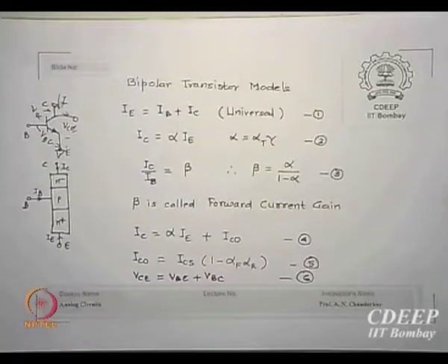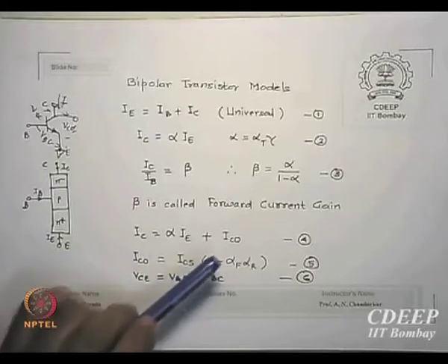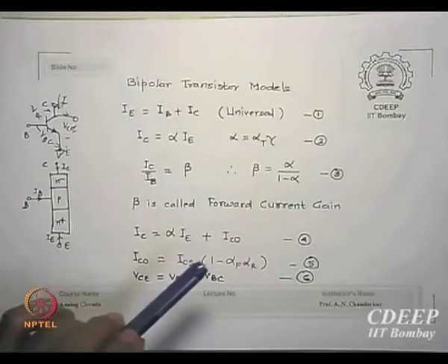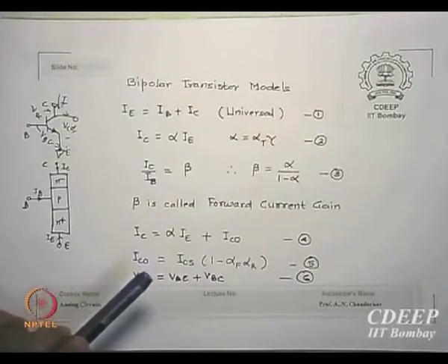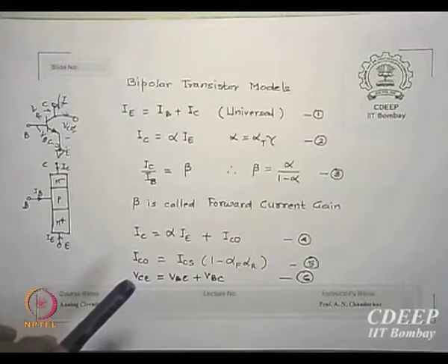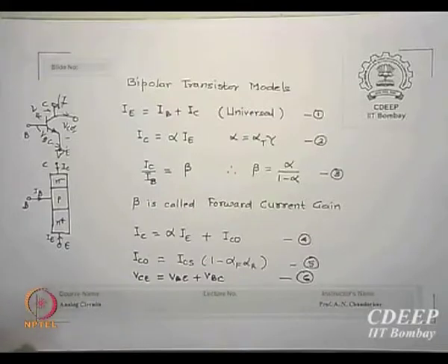And then, in case you are more interested in physics, there is a leakage current coming from the collector, so ICO is that current. Essentially, even if the emitter junction is switched off, that is VBE is negative, current can still flow through the base collector junction, and that's the ICO. That's exactly what the leakage current is about.